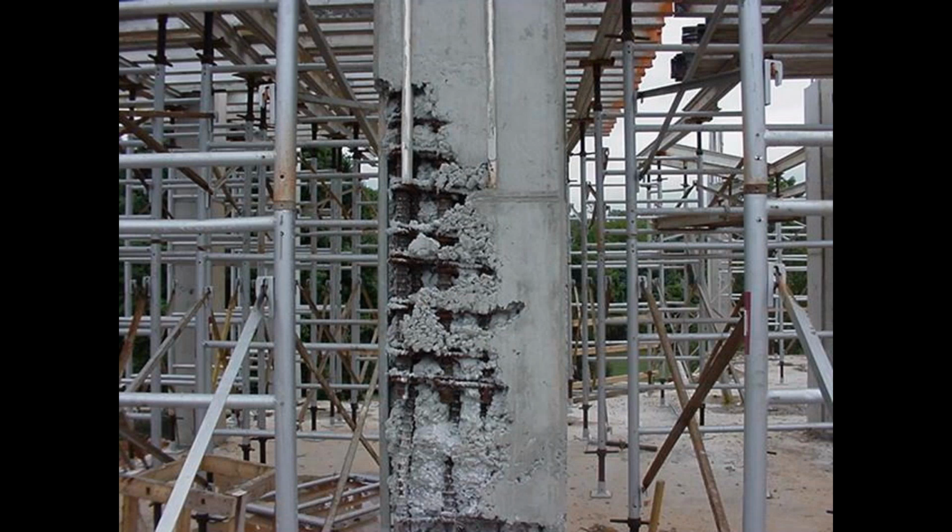And here's a classic example of where we didn't have the concrete flowing right and they didn't manage to get it to the bottom of the in situ formwork, and you've got this. Believe it or not, I've actually seen something like this in a building, and this building was 40 years old, and they pulled the wall cladding off, and we saw one of these. And the more concerning thing is that's actually a column which is load bearing. So therein lies the problem. But these days with skilled concrete places and concrete people around, this is less of a problem. But it's something that they have to deal with.